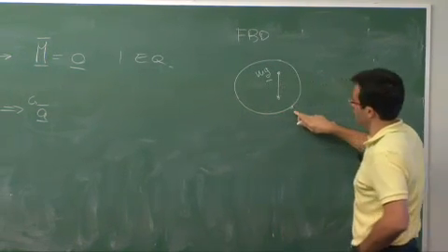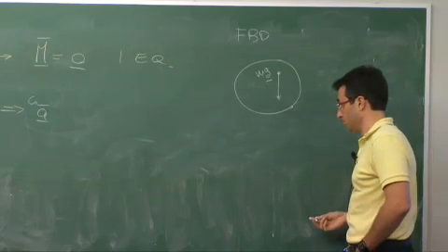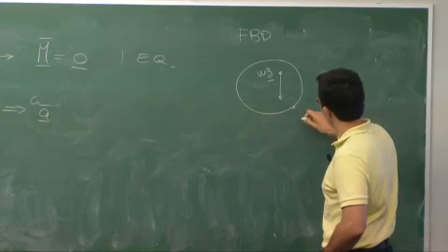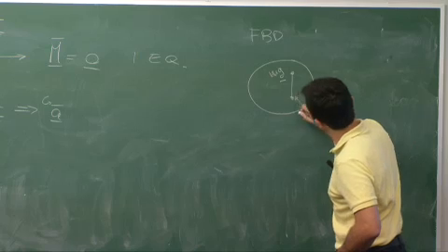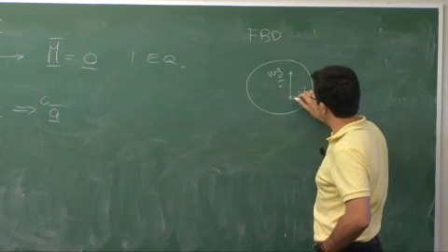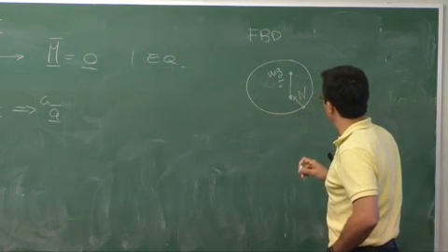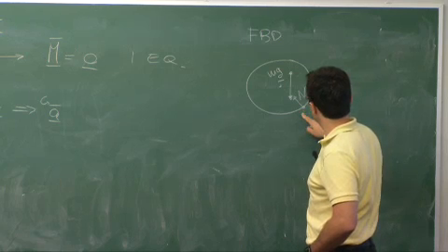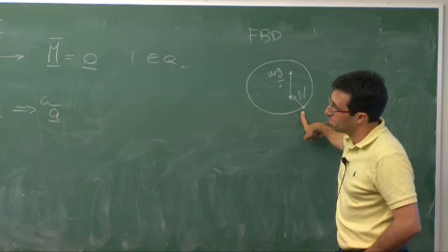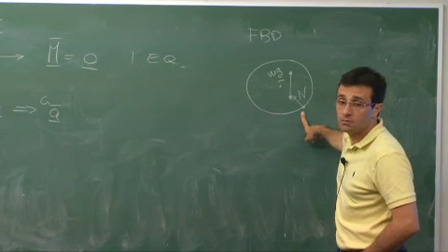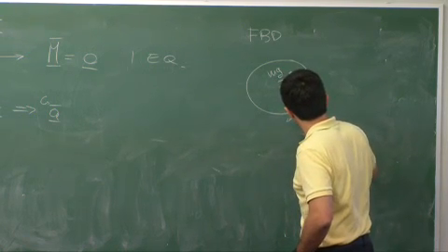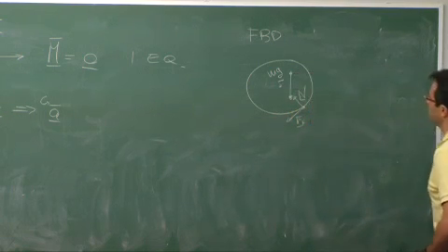And then what do I have here? Did we do this? There is reaction from the guide, which is always pointing at the center. Call it n. But then there must be, we said this the first time we started doing kinematics with rolling as well, there must be some static friction that makes the disk roll, right? So call that F sub F. So we have these two forces here.